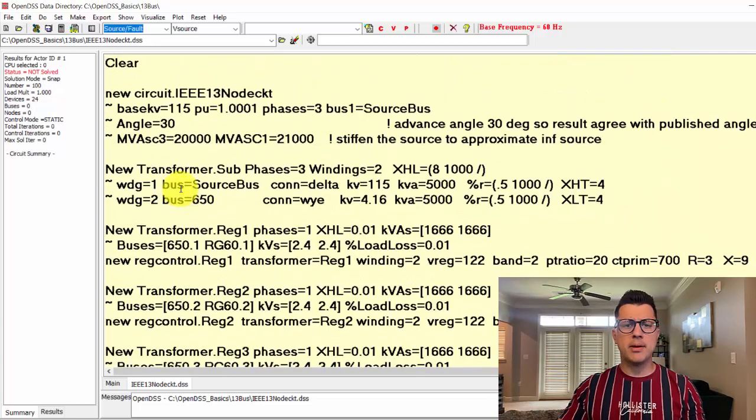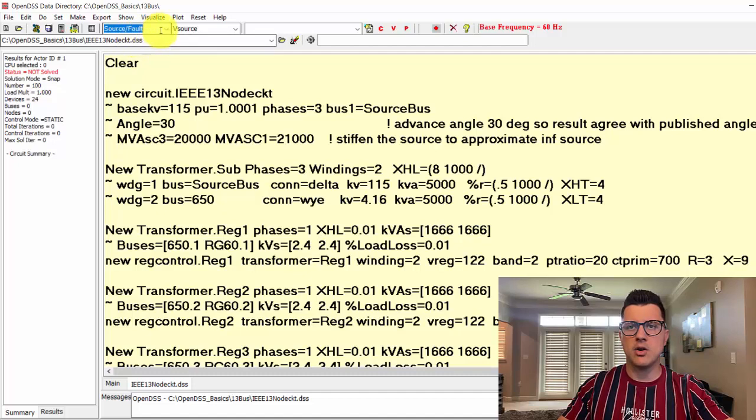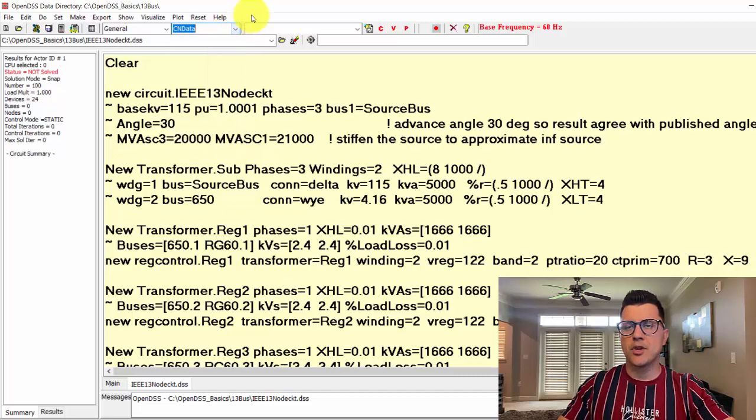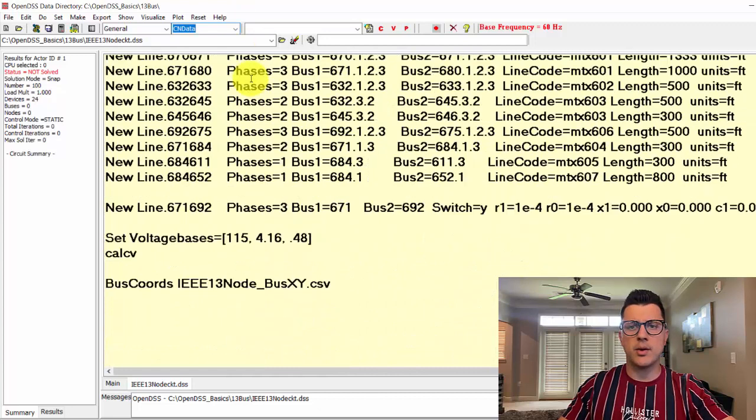And you might be asking yourself, what is general elements? So to check the type of elements we have in OpenDSS, you can go to this section above here. You can go and see that we have PDs, PCs, controls, meters, general. If you set general and then you see the list, those are all general elements. And as you can see, line code is there. Okay, so when you have a general element, it doesn't count. I need to check when we have a meter element if that counts. I think it does, but we can do that later.